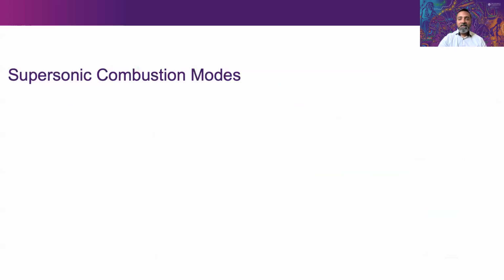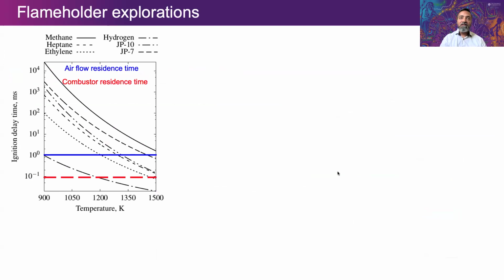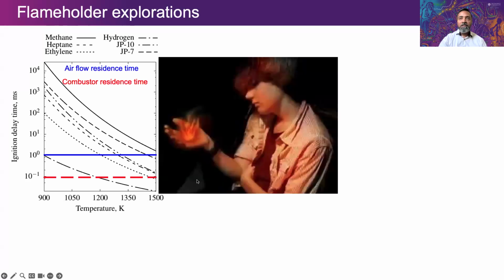But again, coming back to what I said, I'm going to talk to you about, which I'm getting to very slowly, towards the second half of my talk, supersonic combustion modes. So going back to that image I showed you at the start, there is very little airflow residence time to start with, a millisecond, and an even smaller amount of time in the combustor. And when you encounter any of the hydrocarbon fuels, you start getting into the difficult, will it burn sort of question. So we need a flame holder.